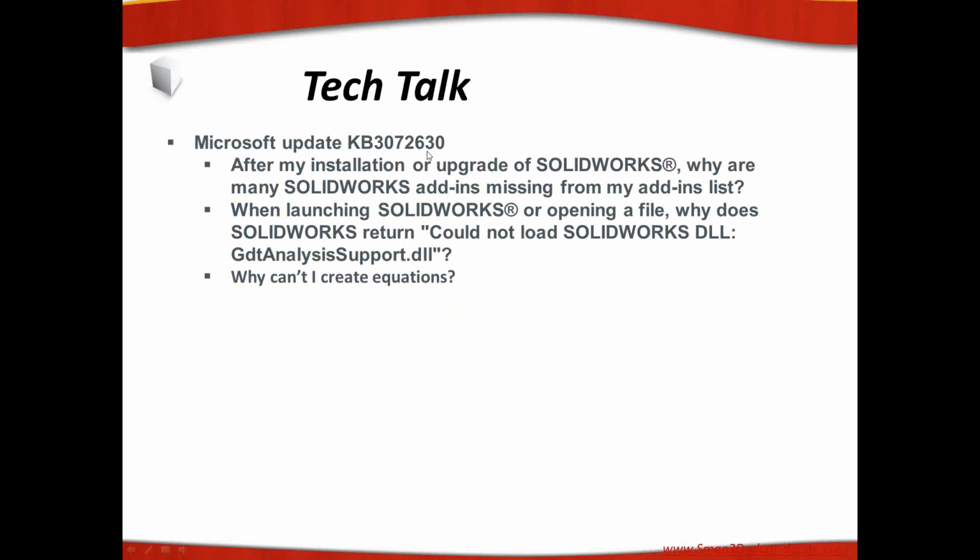And what we've seen is this knowledge base update after it's installed has been causing a lot of issues with the installation of SOLIDWORKS or the upgrade of SOLIDWORKS. Some of the system symptoms you'll see after the installation is upgraded. SOLIDWORKS add-ins are missing. When you go to the Tools add-in window, you don't see many of the add-ins that you saw before. When launching SOLIDWORKS or opening a file, sometimes you'll get error messages, could not load the SOLIDWORKS DLL, and this is analysis support DLL. So if you get some of these error messages as you start working in SOLIDWORKS, also seen where you can't create any equations, that fails as well.